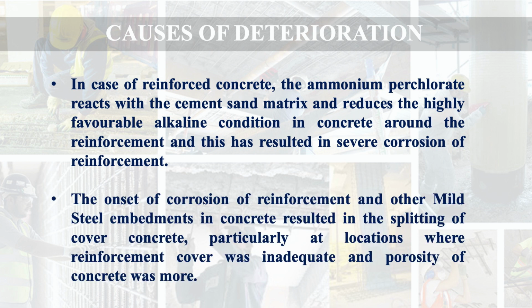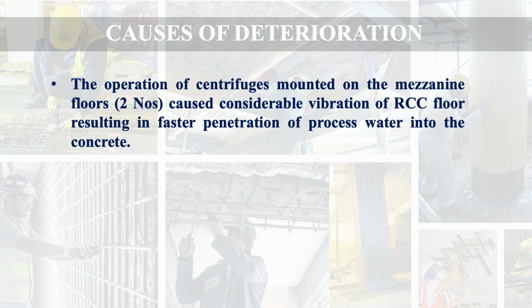The onset of corrosion of reinforcement and other mild steel embedments in concrete resulted in the splitting of cover concrete, particularly at locations where reinforcement cover was inadequate and porosity of concrete was more. The operation of centrifuge mounted on the mezzanine floors caused considerable vibration of RCC floor, resulting in faster penetration of processed water into the concrete.